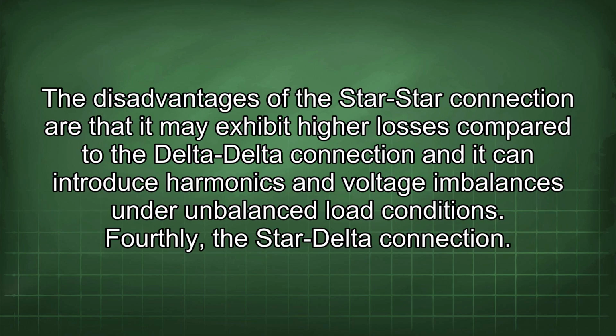The disadvantages of the star-star connection are that it may exhibit higher losses compared to the delta-delta connection, and it can introduce harmonics and voltage imbalances under unbalanced load conditions.